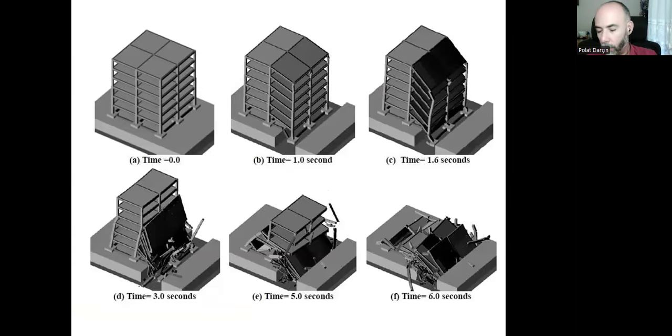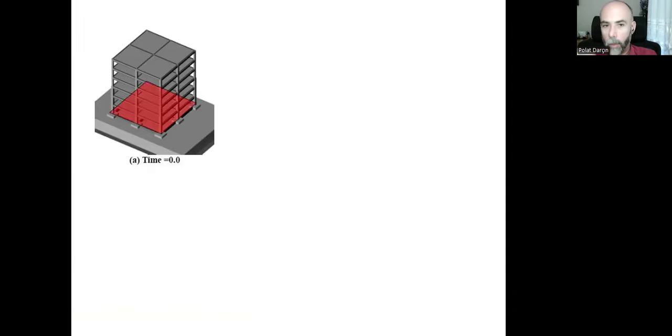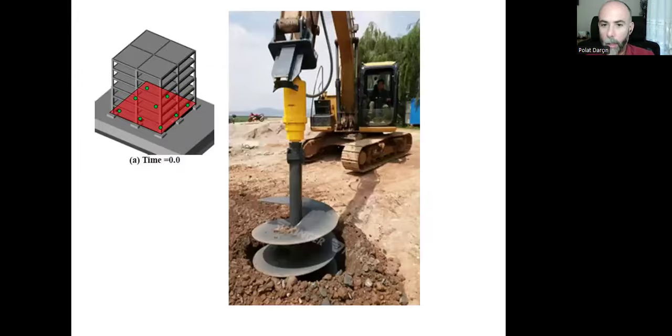If we want to avoid this result, then we need to do not just one boring, but many different borings throughout the area that the building will occupy. And based on the properties of these different areas, we can either design our foundations accordingly or provide certain things in order to make this ground stronger.